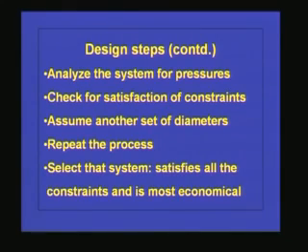At this stage what do we have? We have the network, we have the connectivity of these pipelines, and we also have their lengths and diameters. We would have chosen the material for the pipeline, like asbestos cement pipelines, or concrete pipelines, or galvanized iron pipelines, or plastic pipelines, or whatever. Depending upon the material, you know what is the resistance to the flow of these particular pipelines. All this data we have, we can check for the pressures in the system at different locations by analyzing the system. When you are analyzing the distribution system, you will also be getting the flow rate in each of these pipelines.